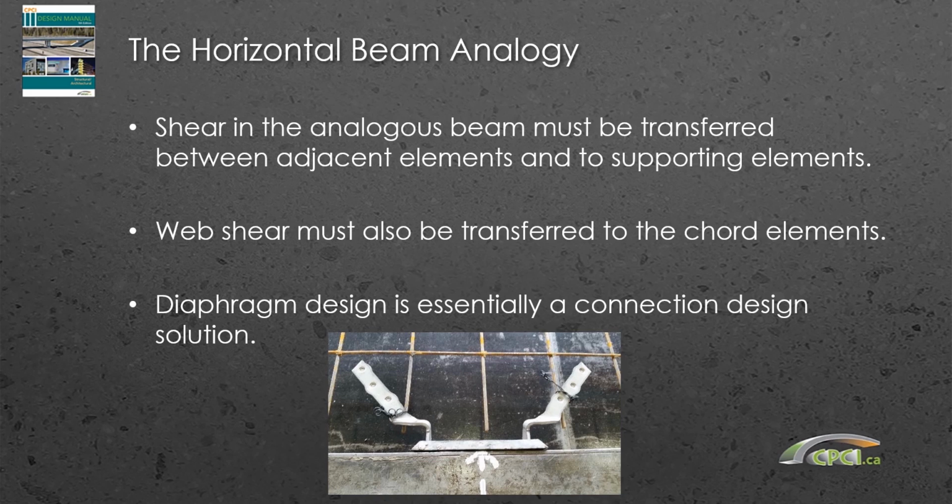The difficulty with designing diaphragms for precast engineers is, compared to cast-in-place floor slabs, where it's monolithic concrete and you can design the overall behavior and reinforcement of that type of diaphragm, precast is made up of individual elements. So we need to make sure we've looked at all the proper force transfer to connect all the elements together and provide the required moment and shear capacity throughout the whole diaphragm.